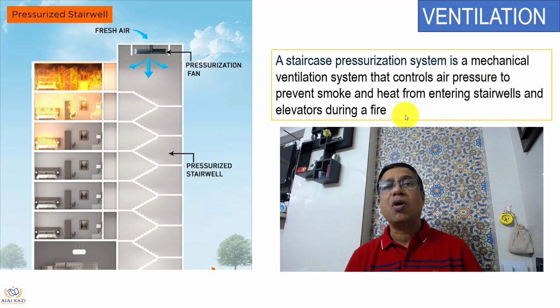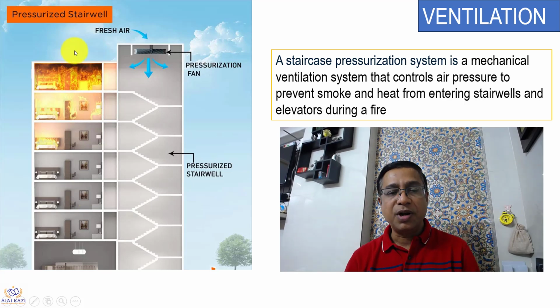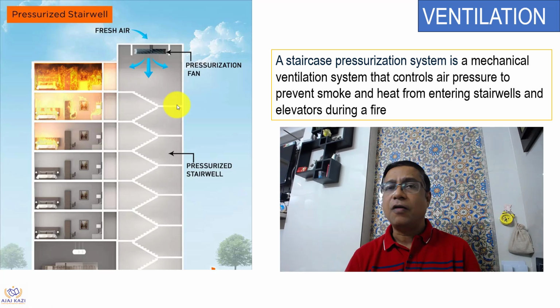Let's look at one of the important applications. This is related to our life safety. This is staircase pressurization, right? When a fire happens on a floor in the building, you must evacuate the people from there through the staircase. If the staircase is outside of the building where you can get natural fresh air, you may not require forced ventilation. We have windows or grills which can bring in that air, and this entire stairwell can get pressurized.